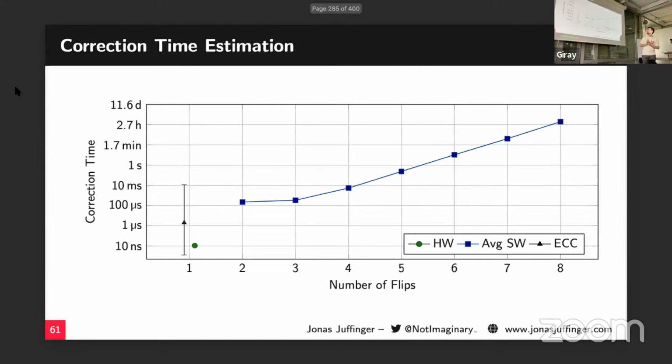Of course. So did you also explore the option of doing some periodic memory scrubbing, in case some of these bit flips are accumulate over time? Maybe you'll see 3 bit flips and then again 3 other bit flips, so instead of fixing 6 bit flips, you can fix 3 bit flips twice. We didn't do an analysis, but there are papers out there that looked at naturally occurring bit flips at a huge scale.